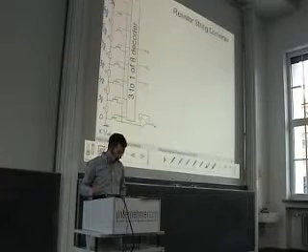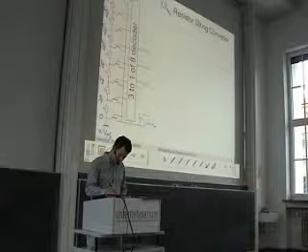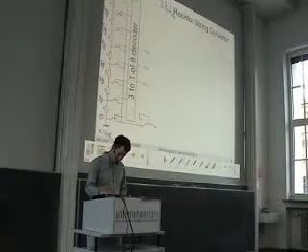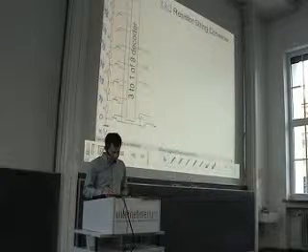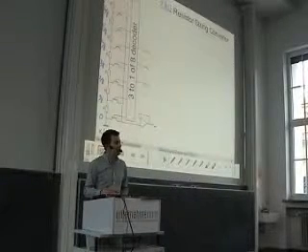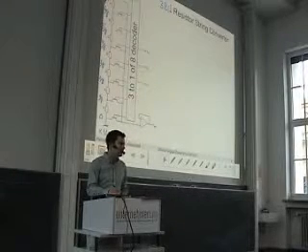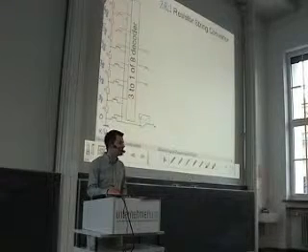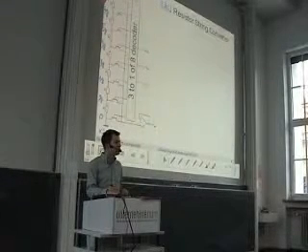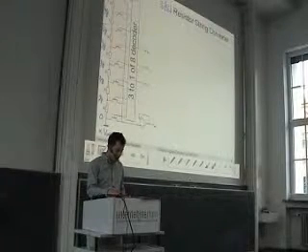So this is a 3-bit resistor string converter. We have 3-bit. And you can recognize the scaling that we already saw in this step function. You can see we do not reach the Vref completely. We are 1 VLSB, which is Vref over 2 to the power of n, below the reference voltage.